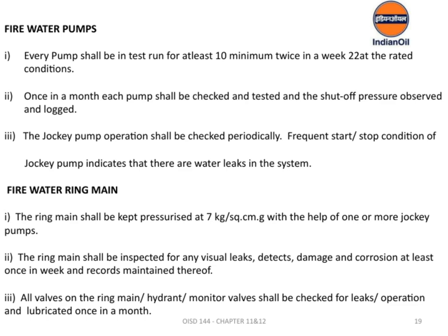We need to verify they operate correctly, check for leaks, and lubricate them as necessary. Proper maintenance of valves guarantees they function correctly when needed most. In essence, these practices, regular testing, inspections, and maintenance, are fundamental to ensuring the fire water system remains reliable and ready to protect lives and property.